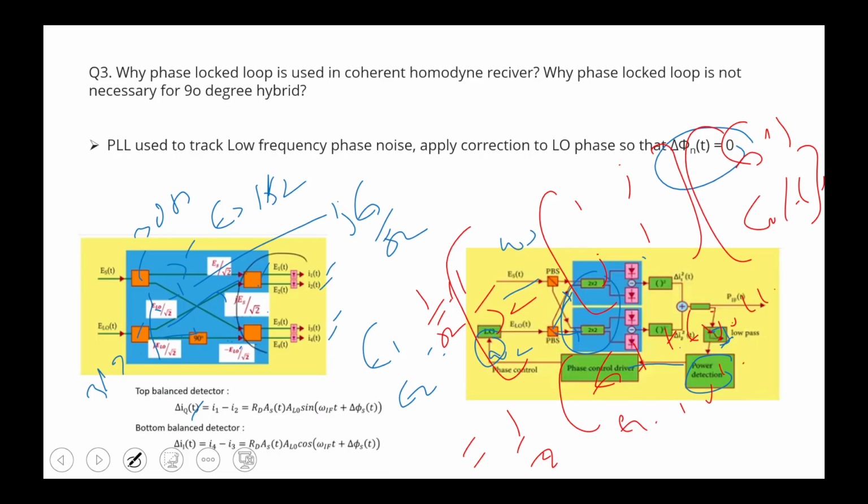So this is one component, and the minus is in the second component, E3 and E4, because the ELO will become positive 90 degrees in this case. So this component becomes Es(t) and ELO(t) in E3 and E4, equal to minus Es(t) and ELO(t). If you multiply both signals, you get I1(t) and I2(t), the quadrature current, and the in-phase current in that case.